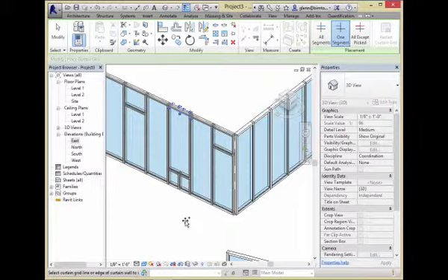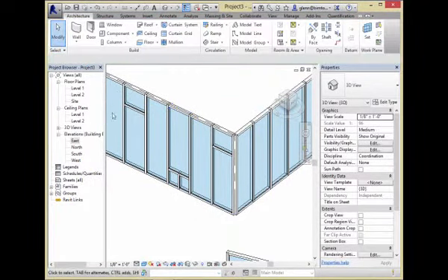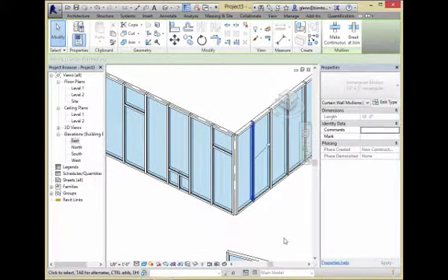One of the few things you have to worry about, though, is that pattern-based walls have the items that were generated by the pattern pinned so that you can't change them easily. If they were generated by the pattern, you don't want to accidentally start messing with the pattern. Let me show you what I mean. If I've got this nice pattern-based curtain wall over here, and there's a vertical mullion here that I want to get rid of, in any other wall, if it wasn't generated by a pattern, I could delete it and it would be gone. Because it came out of the pattern, you see it has this little pin associated with it. What's that all about? That's saying that wasn't just something you arbitrarily put there. That's there for a purpose. So if you want to get rid of it, no problem, we can. But I'm going to make you unpin it, just to give me an explicit acknowledgement that you really do want to make that change.